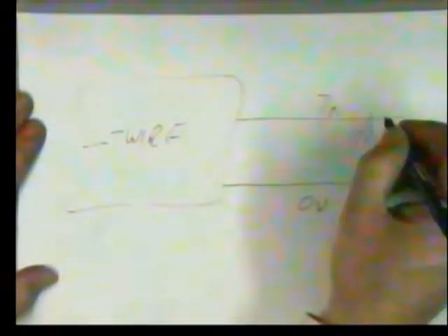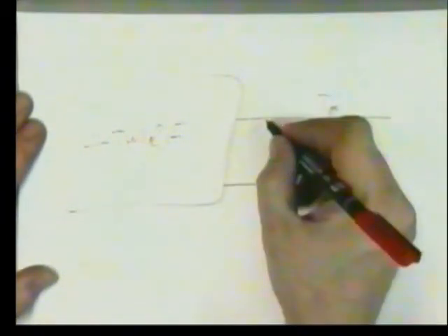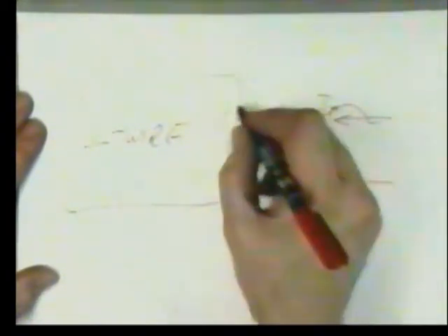So a 2-wire transmitter: we have a single 0 volt reference and we have a single transmission wire, but that combines together supplying the power to our system, and modulated on top of it back again is the transmitted information back to the remote computer.